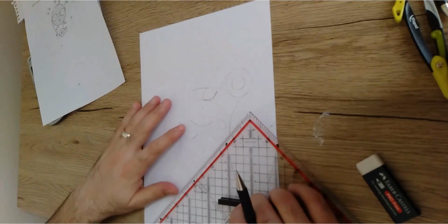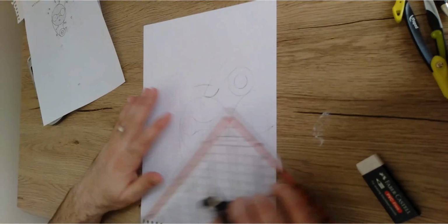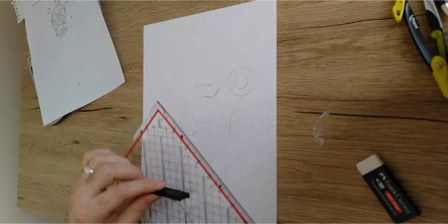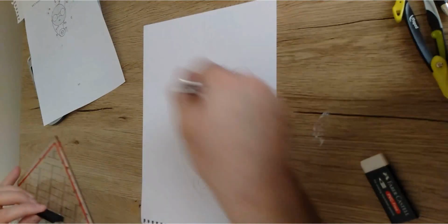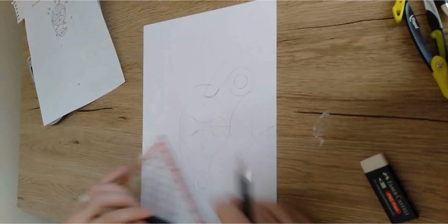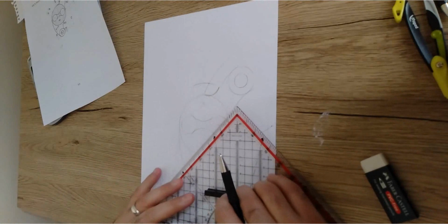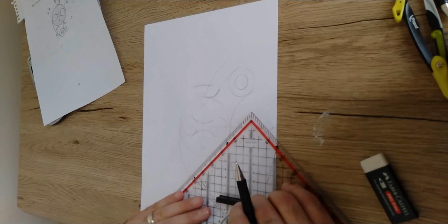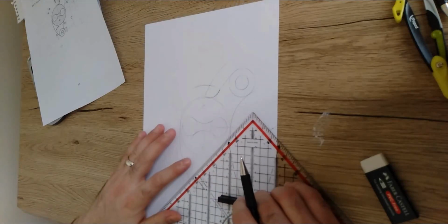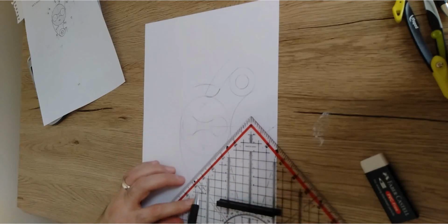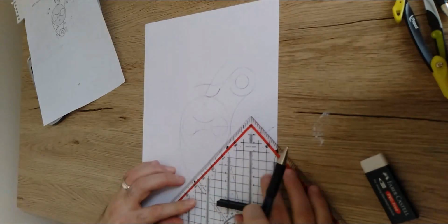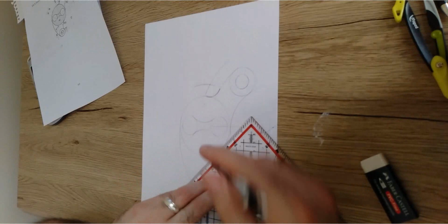So I'm just gonna start here. Make sure that this one is aligned correctly with respect to the edges of the drawing sheet, and that's why I drew these two reference lines in the beginning before I created the drawing. So I'm just gonna use one of these lines, and from the lowest corner of this circle, I'm aligning this vertical line to this vertical line just to make sure that the triangle is located correctly.